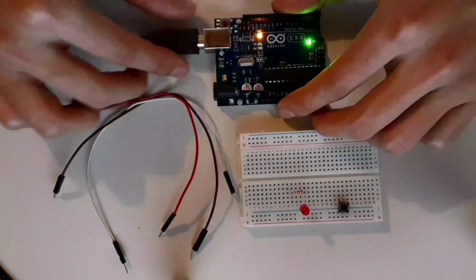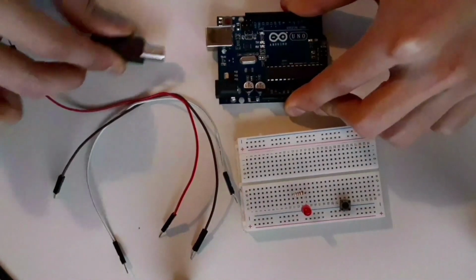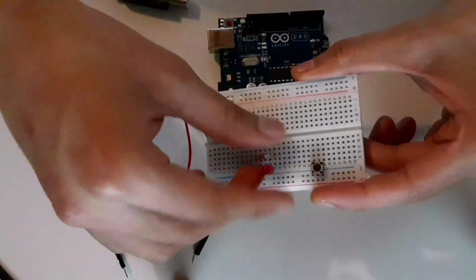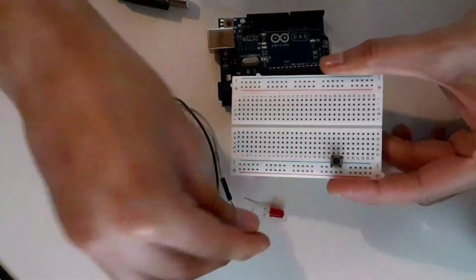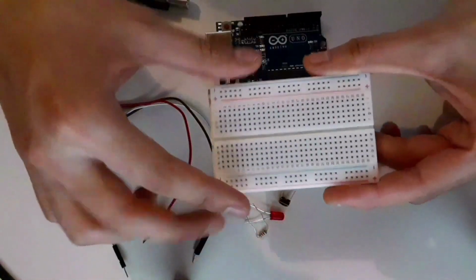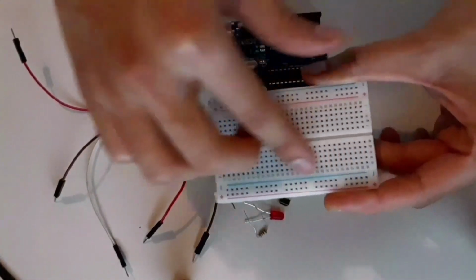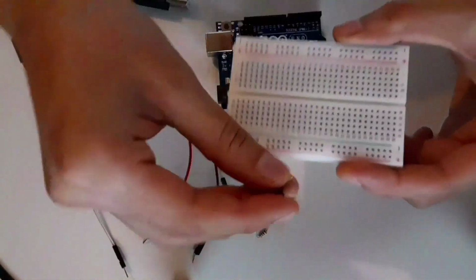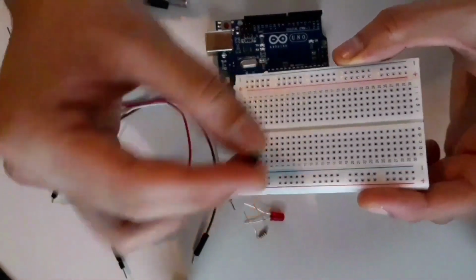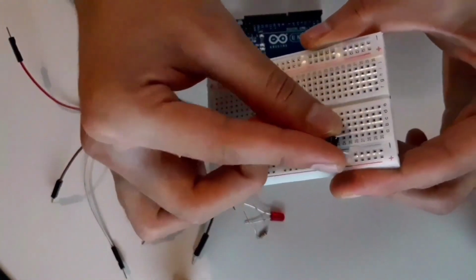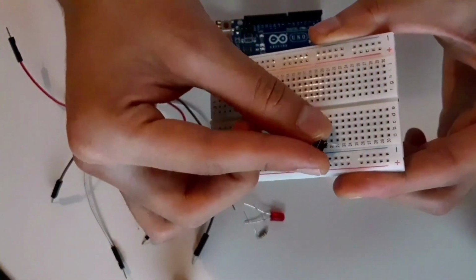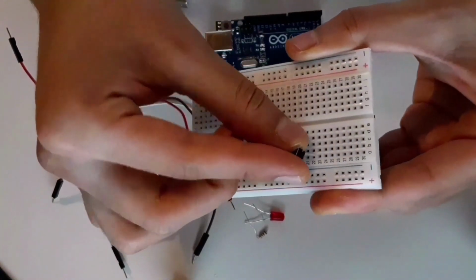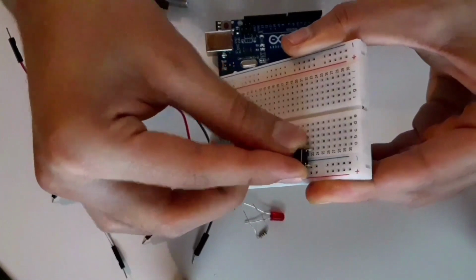I am going to disconnect the Arduino from power or the computer. And I'm going to take the breadboard. I'm going to remove all the components to make it from scratch. And the first thing I'm going to do is to identify this blue line. What is the negative line? And I'm going to take the button. I am going to connect one pin to the negative line of the breadboard. And I'm going to connect the other one in row number 23 of the breadboard. Alright. We're going to connect it. And we just insert it.